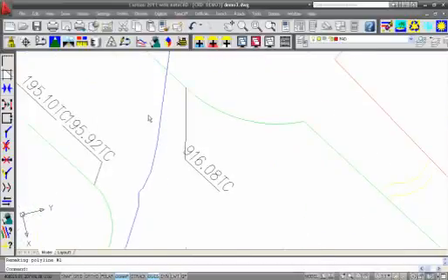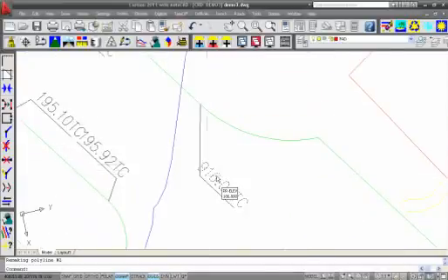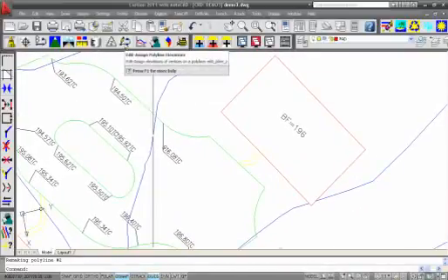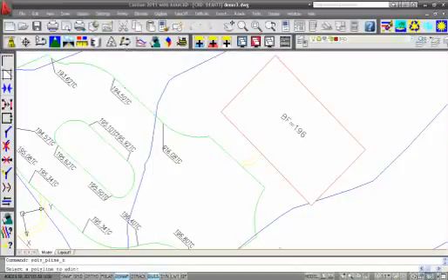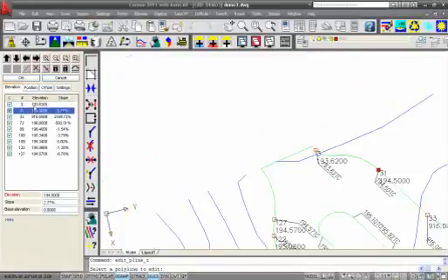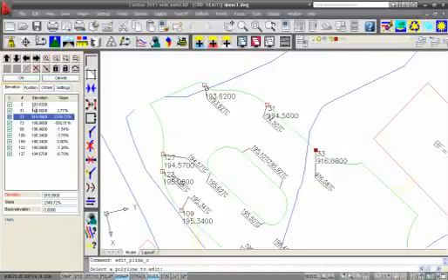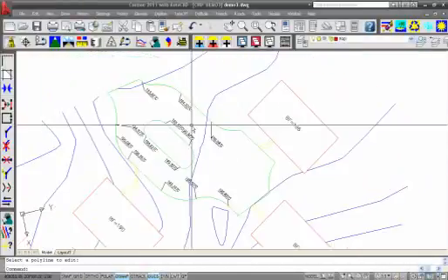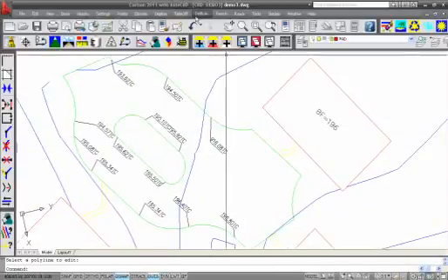You can see this label is incorrect, 195, and this is 916. Those numbers are flipped. If I do edit, assign polyline elevations now, and click on this line, I can see those points, and I could remove 33 from the list here, and it will interpolate through that point. So one of the new Elevate functionalities that we have is the ability to do 2 at a time.